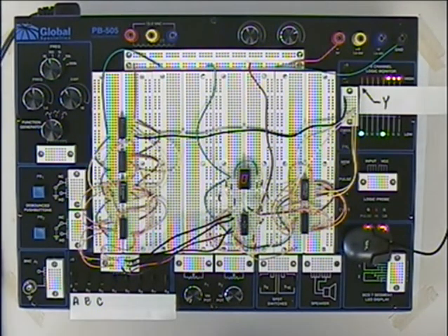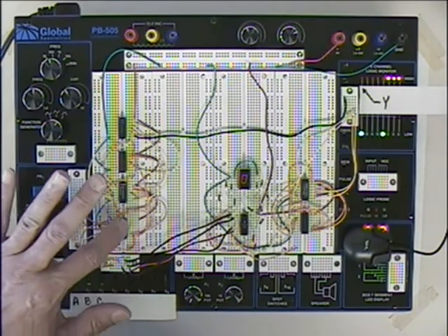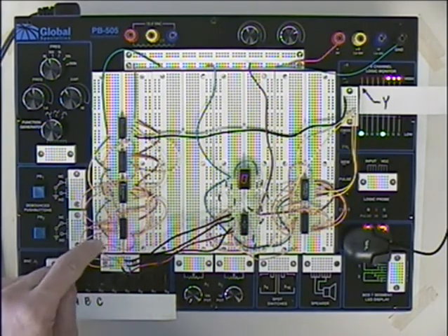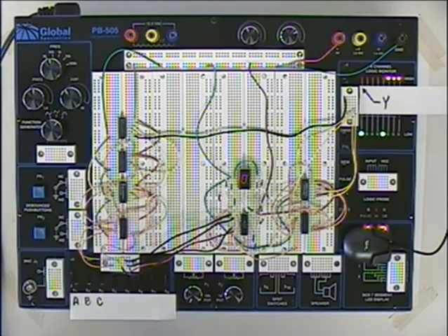And these are kind of fun circuits to build, but they can be kind of frustrating if you're off by one pin. And yours truly, even when I built this thing, I couldn't see as well as I wished I could, and I was one pin off on this thing, so I had to do a little troubleshooting. So the best troubleshooting is to very carefully build it the first time, so you don't have to worry about going around with a logic probe and trying to sort that out.